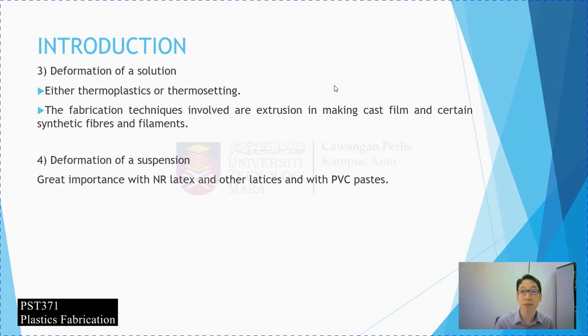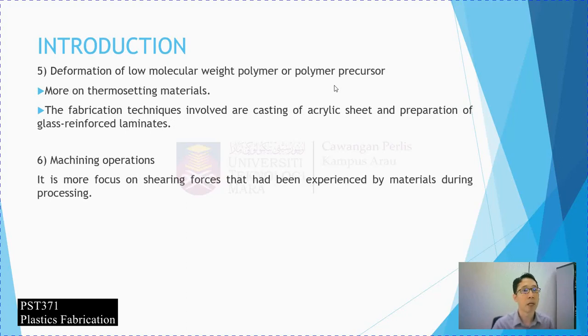That one we call the PVC paste that you transform into a suspension process to produce a foam. Deformation of low molecular weight polymer or polymer precursor, more on thermosetting method. This one is more on thermosetting. The fabrication techniques involved are casting of acrylic sheets and preparation of glass reinforced laminates. This one is more on coating of thermosetting material on other materials such as polymer, ceramic, wood, fabric, etc.